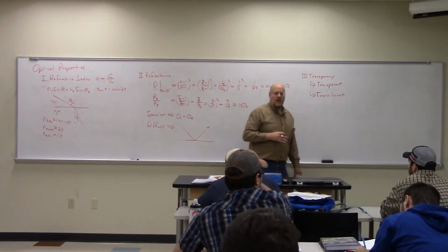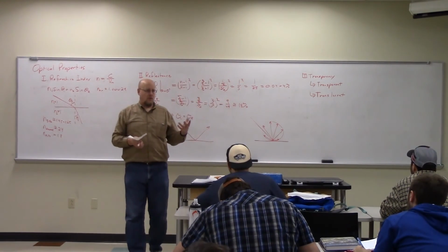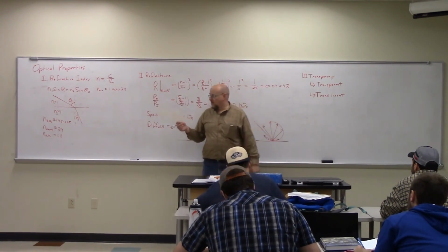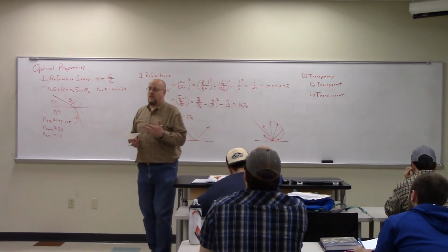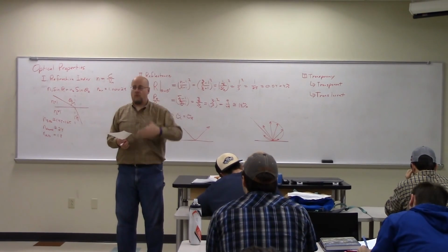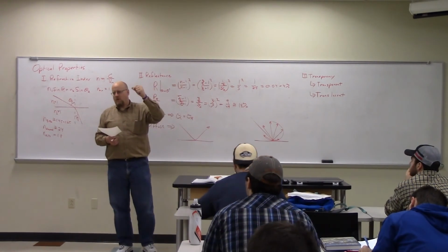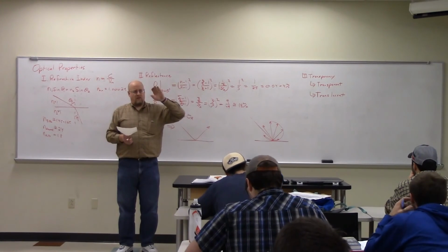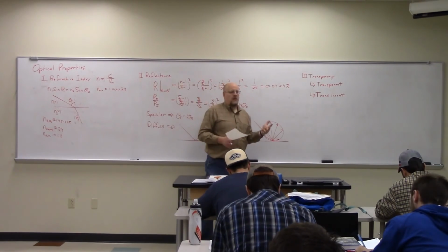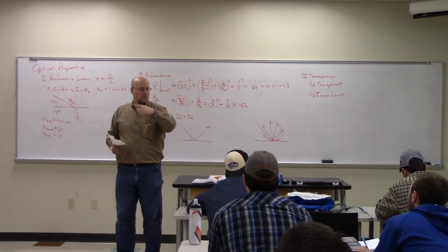That means it doesn't absorb anything. Perfect translucence doesn't absorb light. It just scatters it. So if I have a piece of glass with a bunch of titania in it, titania is actually a transparent medium. You can see through titania. If I had a uniform film of titania, it would be clear. But the titania powder, like I said, has a weird refractive index thing that causes the light to scatter around. So translucency basically means all the light's going through, but it's just not going through in a straight line. It's being scattered into diffuse directions.